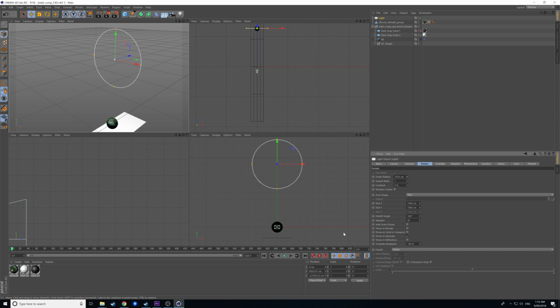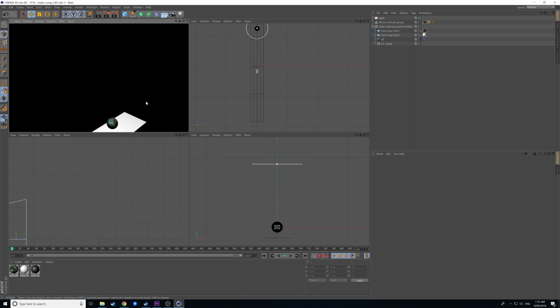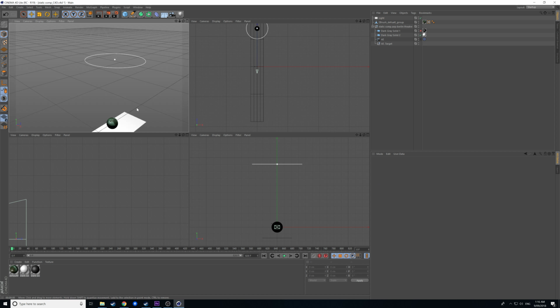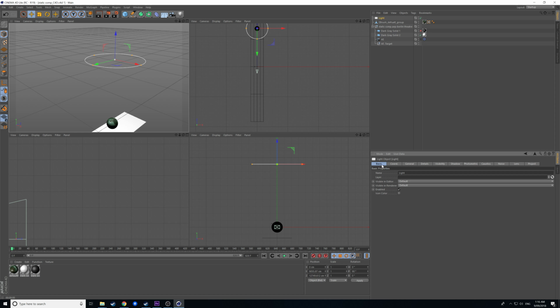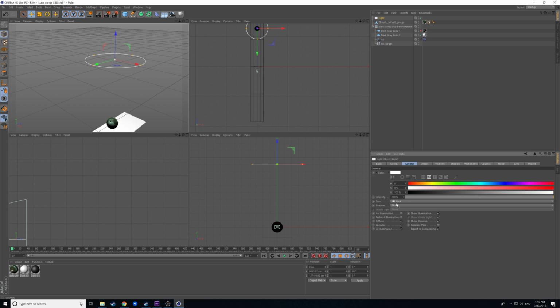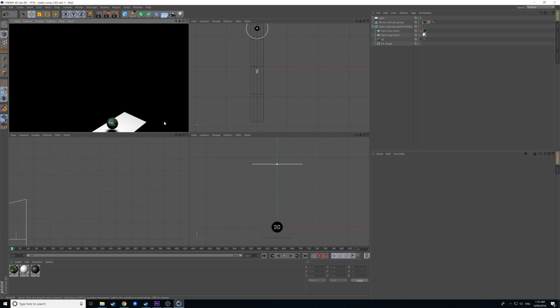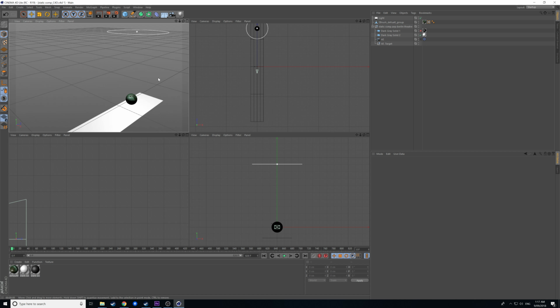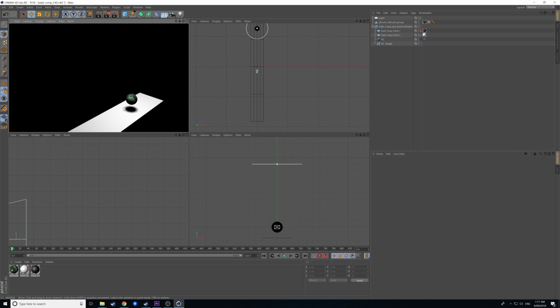And we want to rotate it, so it shines light down. I'll just render it, make sure it's working. Now to produce our shadows, we have to select the light, go to General, and in Shadows say either one of these. I'll just say Soft. Now if we render it, it should apply that shadow there, so we'll just move so we can see that a little bit better. Render it again, and you can see it's producing a shadow onto our placeholder floor, which is perfect.